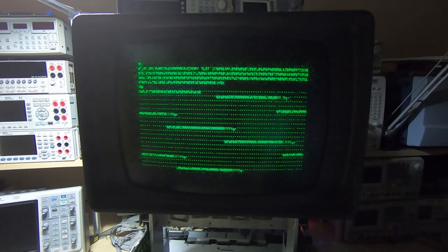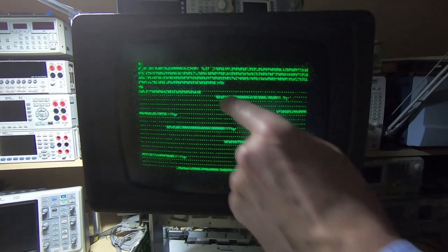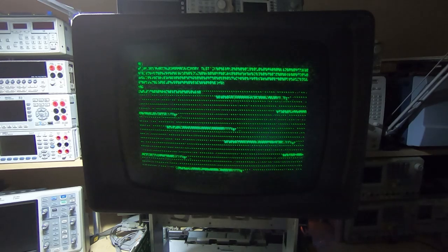So instead of getting a 20 for a space, for example, we're getting a character that represents a value of 60. What's effectively happening here is bit 6 of the character value is stuck, so where we should be getting a space, we're not. We're getting this little hyphen character. That's true of all the characters. Whichever key I press, the character we get is essentially the wrong character, and it's the character you would get if you were to always set bit 6 high. So it sounds like there's an issue with the buffering.